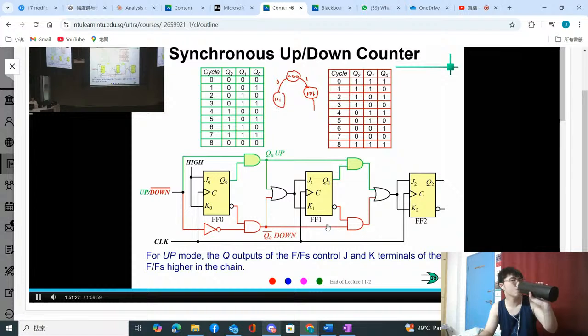If you draw a state diagram, then after that go to the state table, go to the K-maps, go to the flip-flop inputs. There's no output in here. So then you can design the circuit. This is exactly the same method. It's not very difficult. There's only one input. The input is called up, down. Although the name looks very funny, you can call it in. So it is very simple to design a counter, because a counter has no output.